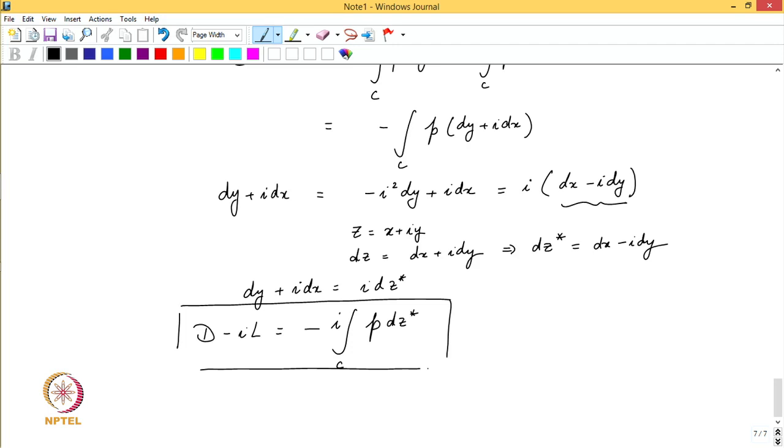So, finally, we need to integrate the pressure distribution over this surface in a certain way, and that would give us the forces. Now, to integrate pressure distribution, we need to first derive the pressure distribution. So, for this we use again Bernoulli's equation, right, because the flow is irrotational, and we use the Bernoulli's equation to correlate pressure in terms of velocity on the surface of the solid.